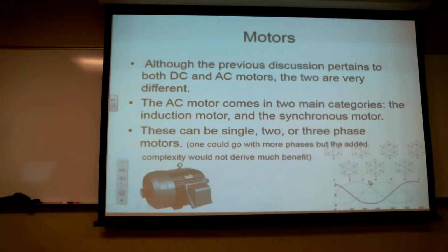So I called him one day because the lathe stopped working. I figured out it shorted one of the wires, one of the 3 phases inside, 440, inside the conduit. So the guy comes out and he's looking at it, and I said, it probably blew L1 there. Yeah, and in fact, you can pull the wire out and it's blown apart. That means it also, at 440 volts, probably fried all the other wires in the conduit. He said, yeah, they're all still working, and I wasn't contracted to look at them, I just fixed the one problem.